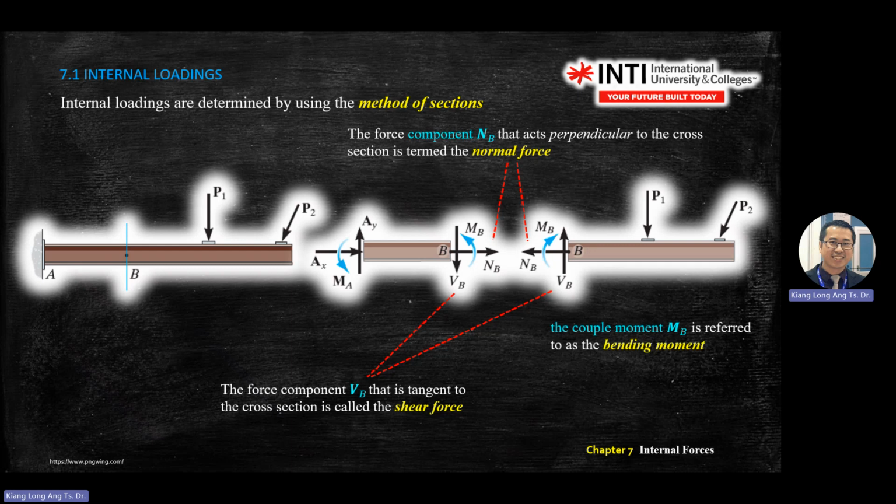Moment means you see things inside there, called bending moment. You bend the thing. So later you need to convert all these arrows into a diagram, into a graph. When you cut the object in the middle, you will have shear loading and you will have bending moment. You have two things inside the body. Again, why is it shear? Because the force is parallel to the area, the cutting area. Why is there a bending moment? Because of the twisting, you can bend the steel.